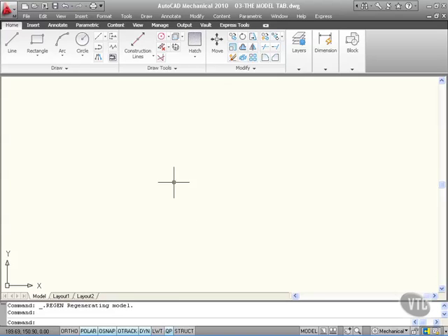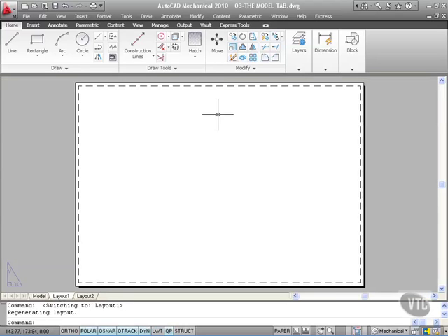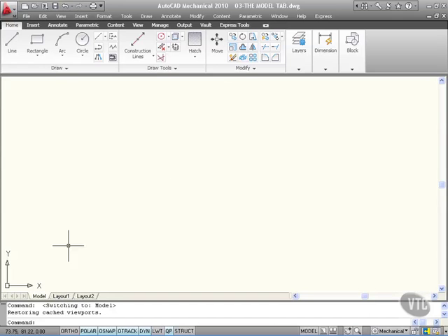For those of you not familiar with AutoCAD at all, work that you do with AutoCAD and AutoCAD Mechanical should normally be done in the Model tab here. And then when you go to your Layout tabs, what you do there is set up your sheet, your title block, your viewports and so on, so that you can view scaled views of what's actually in the model space, the Model tab here. Now, what we're going to look at very briefly is how the Model tab works.